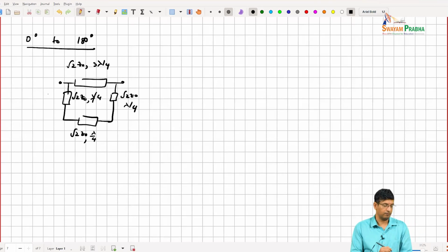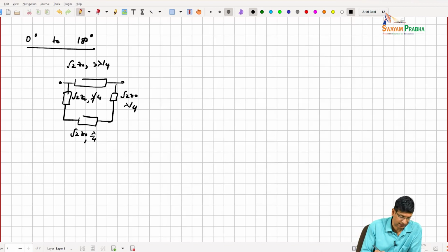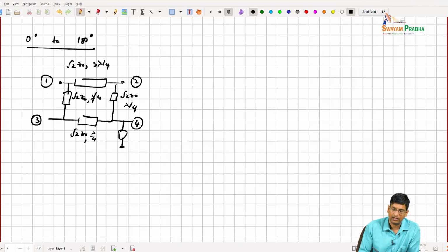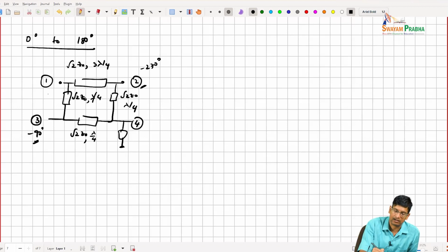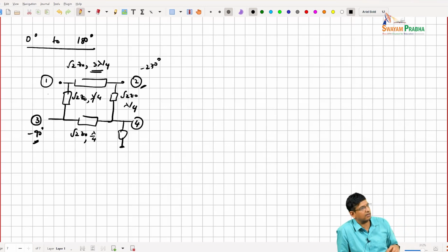With this kind of structure, you can basically have port 1 and then this over here is your isolated port. This over here is your port 2 and this is port 3. You can see intuitively that this is sort of minus 270 degrees, this is sort of minus 90 degrees, from the length of the transmission lines. So you can get a 180-degree phase difference between port 2 and port 3. But clearly these are extremely long transmission lines. So building them on chip can be lossy and area intensive.